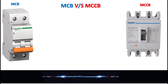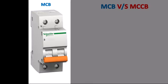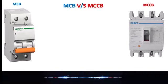In electrical systems, both MCCBs and MCBs are used to protect circuits, but they serve different purposes and are used together in certain applications. Let's break down how these two work together. An MCB is a small circuit breaker typically used for protecting smaller circuits with lower currents, usually up to 100 amps. It's commonly found in homes and offices to protect individual circuits from overload or short circuits.